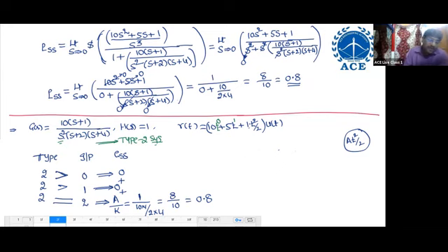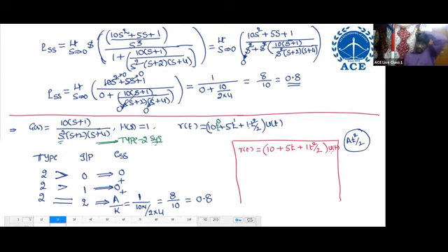Now there is even no need to write like this. Directly we can write the steady state error. How to write? For example, what is R of t? Tell me: 10 plus 5t plus 1 t squared by 2. Now, if you find the steady state error...